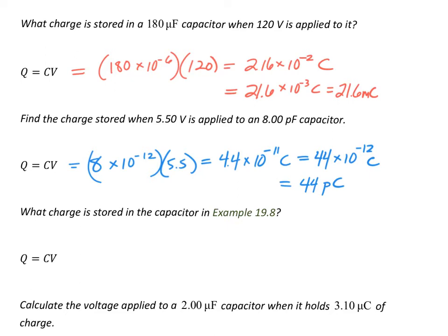Charge in these examples is directly proportional to the capacitance of whatever that charge is resting on and the voltage applied to that thing. More voltage would mean more charge, because more voltage means pushing more charge around. More capacitance would mean more charge. And so what is capacitance dependent on? Well, one of the equations, if I remember correctly, is the area per distance, and then the electric permittivity constant is out in front of that. So directly proportional to area, inversely proportional to distance.